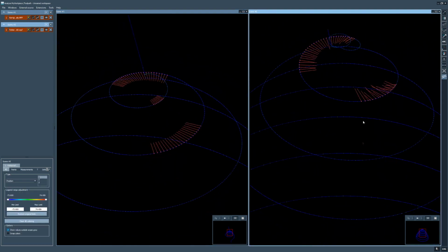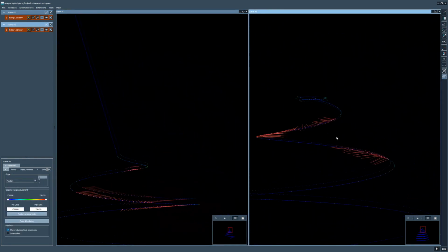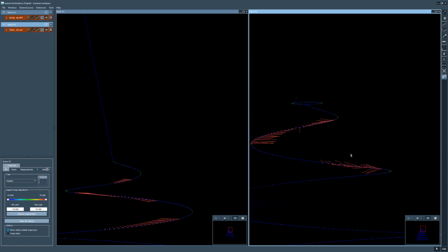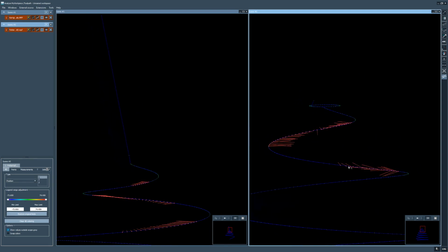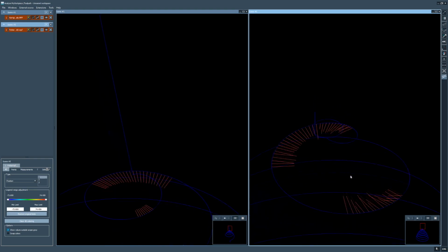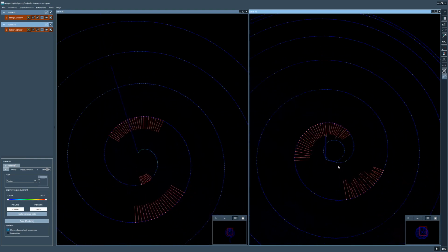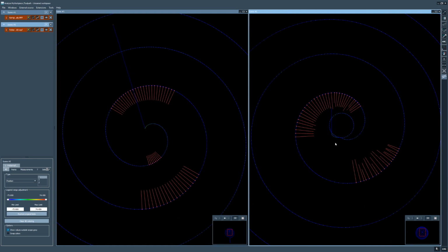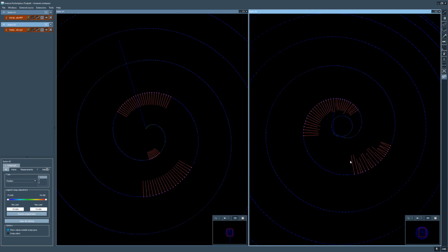The curvature is not really steady here. Even if we check how it is distributed alongside the plane, we can also see that on the right the situation doesn't look really good. Therefore, the curvature reveals that we can expect speed drops in this area, because the mechanic will try to follow this path like that, and that will slow down certain axes.